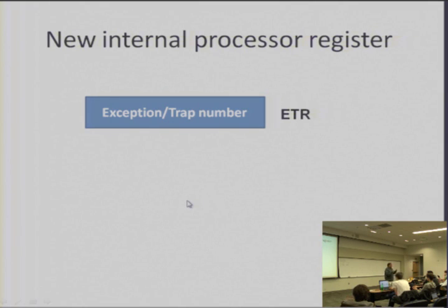So that way, what we've done is, we were doing a program execution, and suddenly there is an event that causes a discontinuity, and the source of the discontinuity is registered in this register. Is that idea clear? You can see that in hardware you can actually do this. So it's not magic anymore. You can generate a unique number corresponding to each source of discontinuity and put it into this register internal to the processor. I want to make sure that this idea is clear, because the next thing that we're going to do